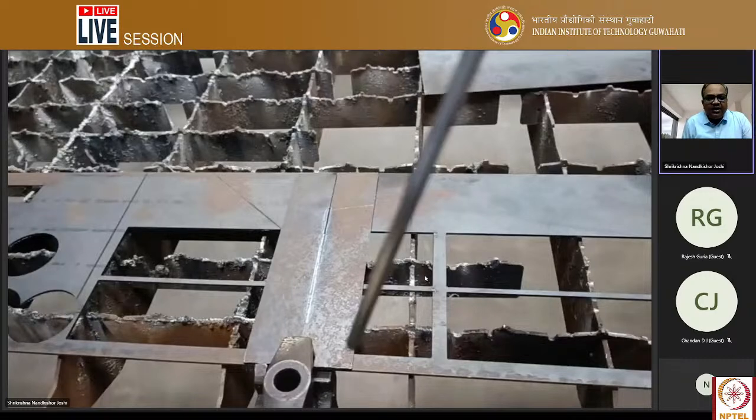Fine. And in the previous week, you have seen the laser-based forming operations as well. How lasers are useful to plastically deform the material without contacting it. We have seen the TGM, BM, and UM, temperature gradient mechanism, buckling mechanism, and upsetting mechanism, and various theoretical aspects related to laser forming. In addition to that, one small video was also shown to you. So with this, we are learning how lasers can be helpful for us in manufacturing operations.